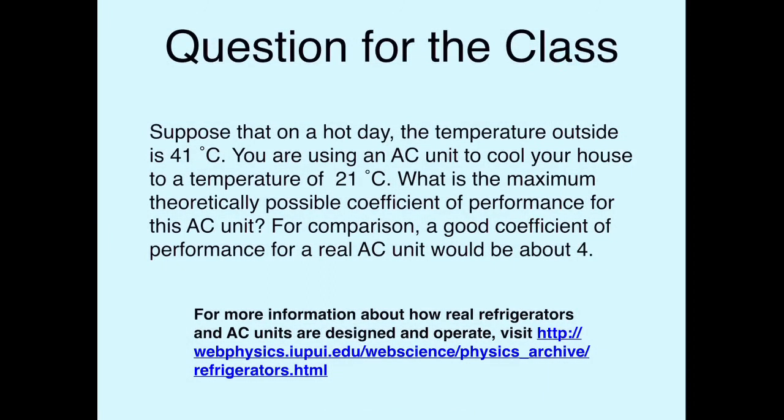Okay, so let's get a little bit of practice using that result. Suppose that on a hot day, the temperature outside is 41 degrees Celsius. You are using an AC unit to cool your house to a temperature of 21 degrees Celsius. What is the maximum theoretically possible coefficient of performance for this AC unit? So in other words, calculate the Carnot coefficient of performance. And for comparison, a good coefficient of performance for a real AC unit would be something around 4, okay?